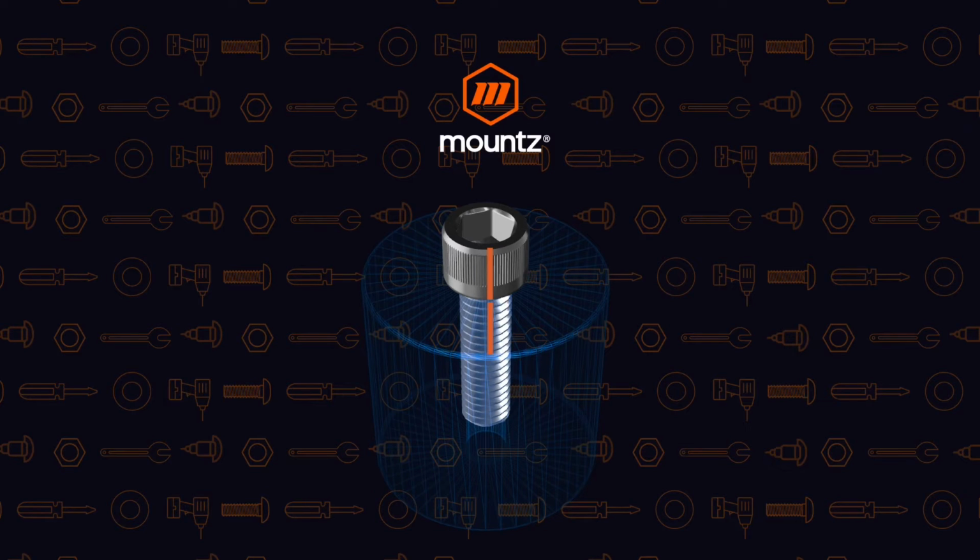For example, you may have a coefficient of friction over 1 when you've got 2 aluminum parts because there'll actually be adhesion that happens when those parts come together. So it just depends a lot on the material. But again, you want to be able to develop what the correlation is between the values that you're seeing and the values that your tools are producing.